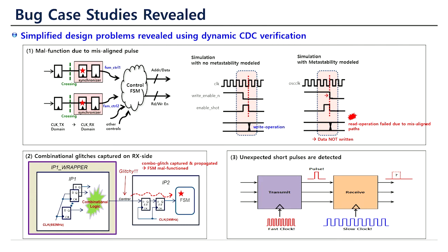But there is logic in the circuit between the two synchronizers, and it is touching the state machine transitions, and the designer didn't know what happens under metastability stress.